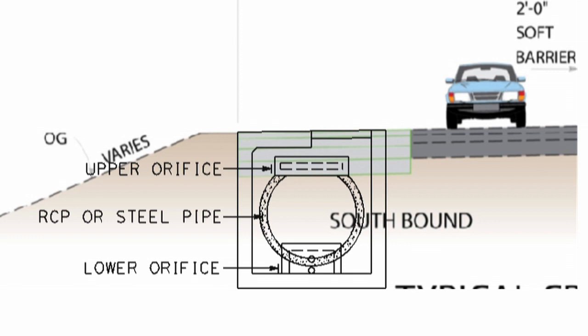For the storage pipes, we can place them under existing pavement shoulder or pavement structure, thus no right-of-way acquisition, thus no increase in cost, no schedule run-off. There are two additional benefits to the use of storage pipes. One, it can be easily integrated into the proposed drainage system. Second, it's easy to maintain because of the placement of screens.